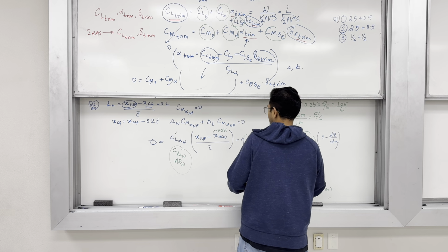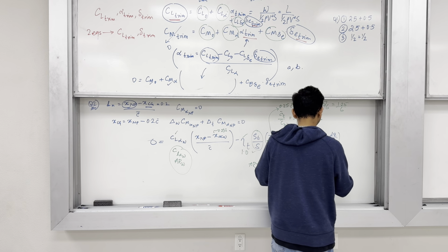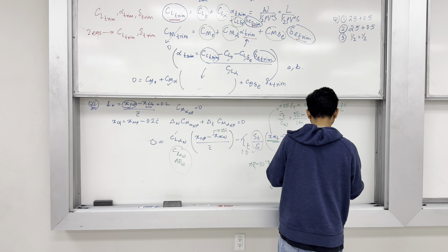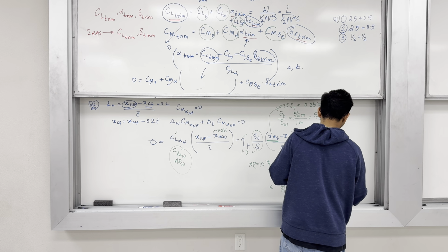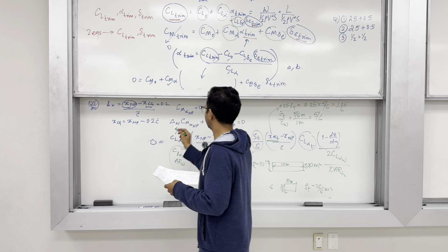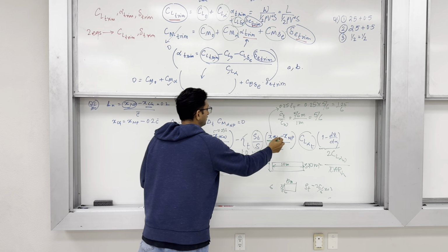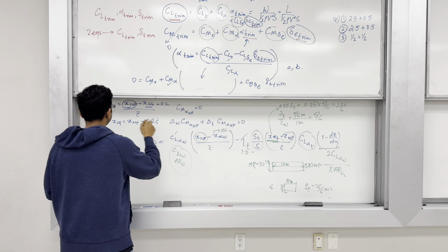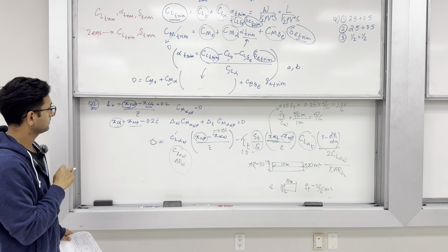CL alpha tail, the same way that you found CL alpha wing, and 1 minus d epsilon by d alpha, use the 2D lifting line theory to approximate it by 2 CL alpha wing divided by pi AR wing. Everything in the equation is now known and you can express the value of x neutral point. Once you have that, you go and feed it in here, you have the location of the CG.